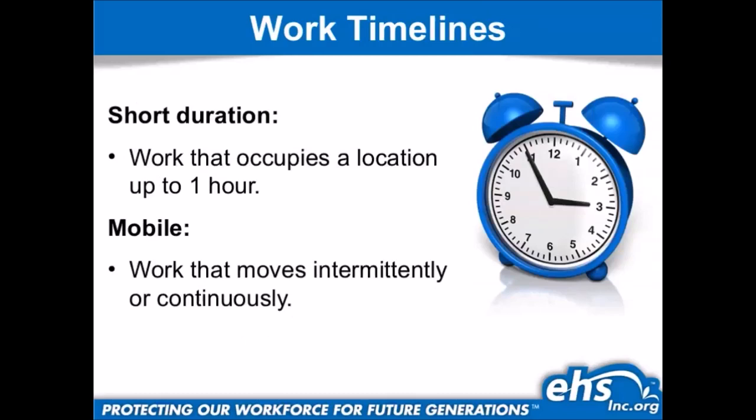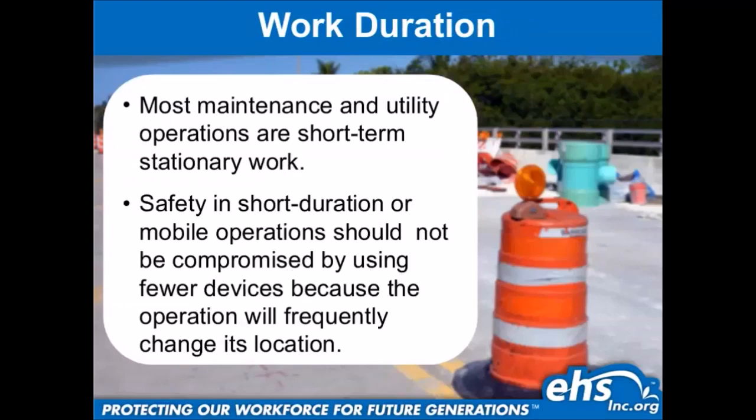So I'll have guys that'll say, hey, well, we're only going to be out here half an hour. Should we set up the cones? The guidelines don't necessarily say I have to. And then I'll let them know, yeah, well, the guidelines are exactly that. They're guidelines. The goal, again, in traffic control isn't to meet compliance. The goal is to make sure that these guys are getting to work each and every day and coming back home in the same condition they got to work. So the guidelines are just a guideline, but it should never be exactly what's followed.